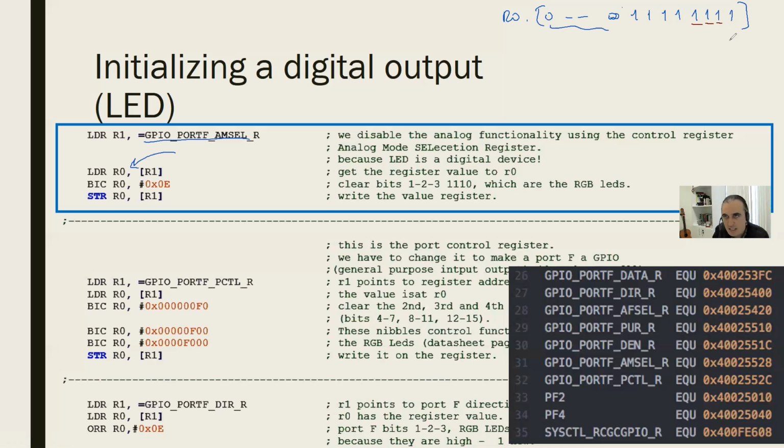So this is E. What is E? E is this, guys: 1, 1, 1, and 0, and the rest is 0. Assume 0. This is 0E, guys. And I'm defining the bit clear operation here. Bit clear means look at the mask, and if the corresponding bit in the mask is 1, make it 0, clear it.